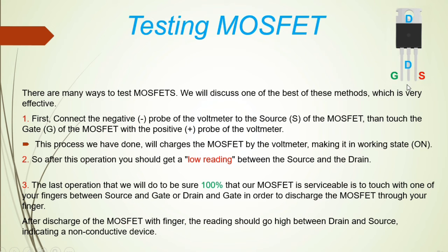Okay? So if after charging the MOSFET we touch between gate and drain with our finger, or between gate and source, the MOSFET will be discharged through our finger.